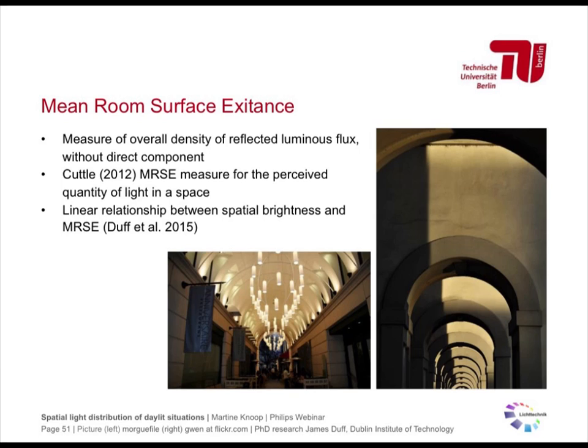Both James and Raphael found that the luminances of the wall were very important for the perceived brightness of a space. But they also both confirmed in their studies that horizontal luminance is not representative for the spatial brightness or visual lightness. If we look at these two pieces of research, one could conclude that the luminance of the room surfaces needs to be included in the standards, and I absolutely agree on that. But the lighting quality of a room is not secured with that.